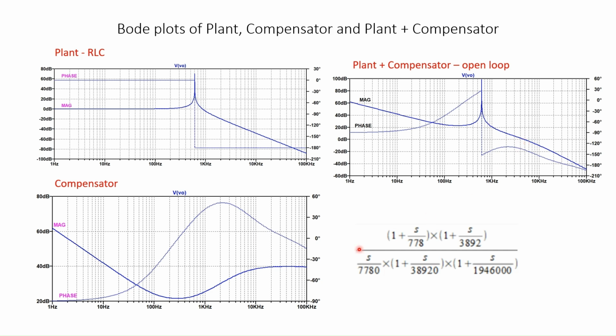And since the net magnitude plot is going to drop at 20 dB per decade because of 2 poles and 1 zero, it crosses 0 dB at 20 dB per decade, which is a single pole. And there is another pole coming immediately after that. So that will give about 45 degrees. So 90 degrees plus about 45 degrees, about 135 degrees is the phase expected at this point.